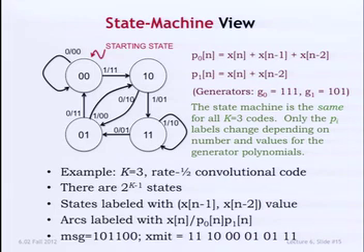If you've got a constraint length of k, you've got 2 to the k minus 1 states. That's because in that constraint length, one of the bits involved is the input bit, which is not sitting in the shift registers. So you've got k minus 1 bits left over, so your shift register is k minus 1 stages long, and you've got 2 to the k minus 1 states. So you could imagine generalizing this to more complicated situations.